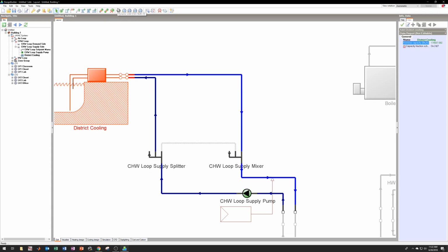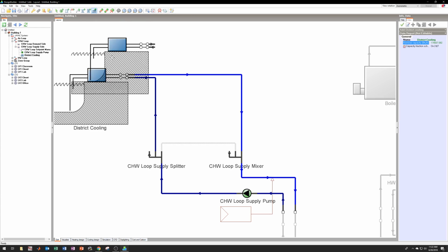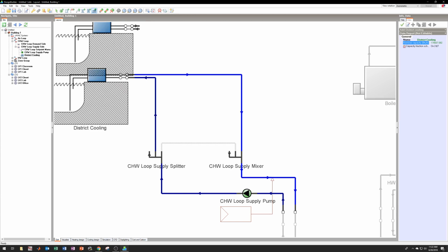If you run the simulation and you see that the cooling supply cannot satisfy the loads, just add another chiller, increase the value, and then connect them as you did into the in and out, and that'll let you have any amount of heating and cooling you desire.